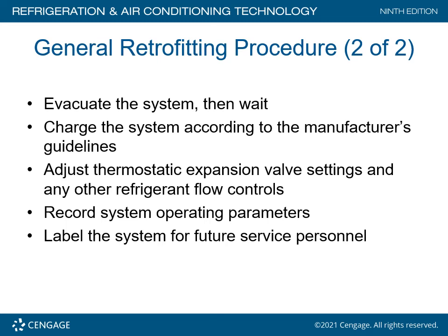And then the other problem is this. When you go to change out the system, now you have mixed refrigerants. These refrigerants can be, in some cases, separated out, but it's expensive. You've created a can of worms. And what am I saying? I'm just saying, do not mix refrigerants. If you have an R22 system and you do not have virgin R22 on your truck to fix the system charge, pull out the remaining R22, employ the retrofit guidelines, and utilize a substitute refrigerant.